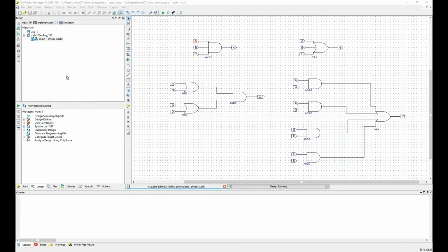In order to do that, you need to add a source in the existing schematics you have. So this is the schematics we are talking about. Now we have to add a source to implement the test bench. So let's see how to do that. First, you have to select this one, and then you can click to add a source, or you can put a new source in here. So let's go to that one.